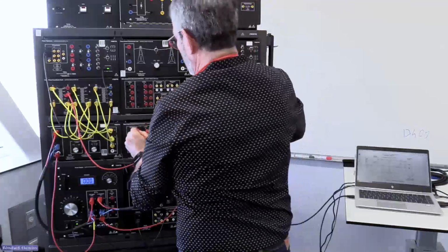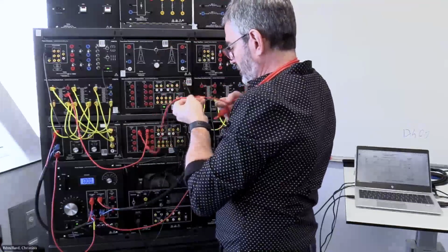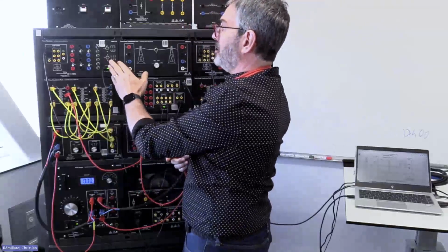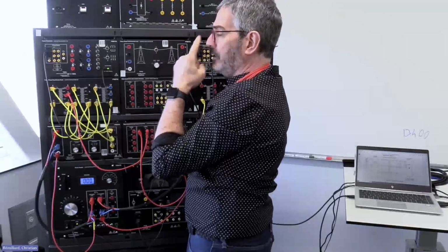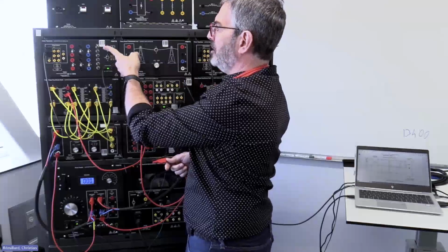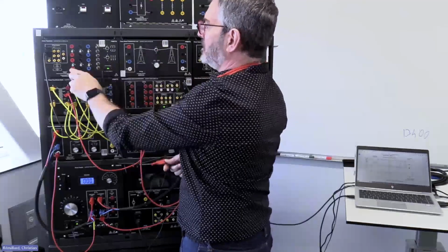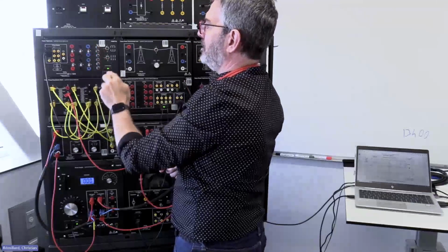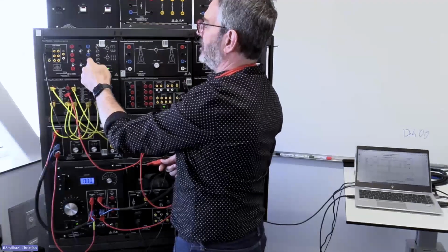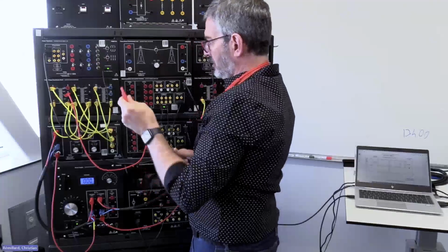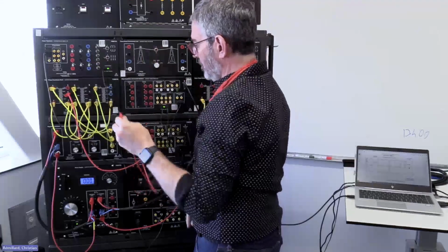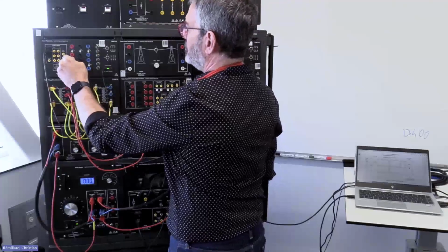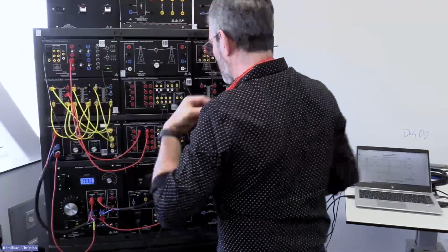From there, we'll go to the thyristor bridge. Note that the thyristor module needs to be set as in the exercise with the two switches here set to on. In this case, it means that we have these 3 points connected together, these 3 points together here, and this is also connected like this. So it makes the three-phase connections much easier. So I1 will go to phase 1. Of course, any of these two ports will do since they are connected together.